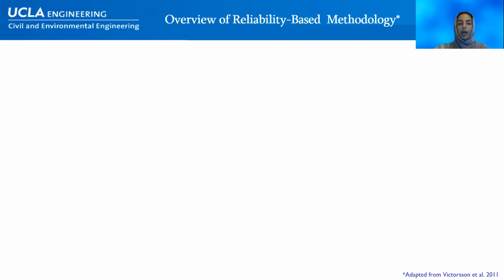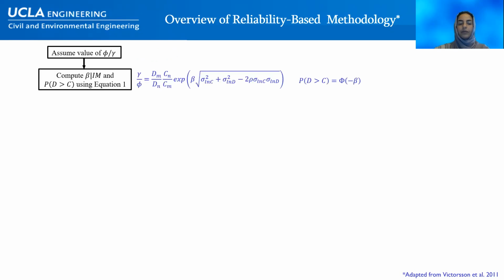In this slide, I will give an overview of the proposed reliability-based methodology. The first step is to assume a value for the ratio between the resistance and load factor used in the LRFD-based design. Then, assuming a lognormal distribution governs the probabilistic demands and capacities of the braced frame elements, we can use these two equations to compute the reliability index for the force control component and the corresponding probability of